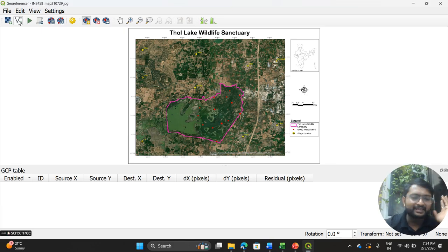Do you think that vector data, which we generally create over a map, might also need to be digitized or georeferenced sometimes? When we need a specific transformation, we have to reproject or re-georeference. Then we usually do this type of vector georeferencing.